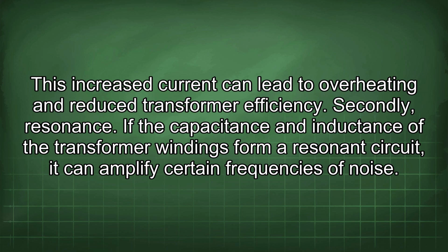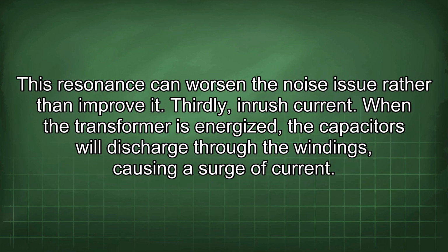Secondly, resonance. If the capacitance and inductance of the transformer windings form a resonant circuit, it can amplify certain frequencies of noise. This resonance can worsen the noise issue rather than improve it.